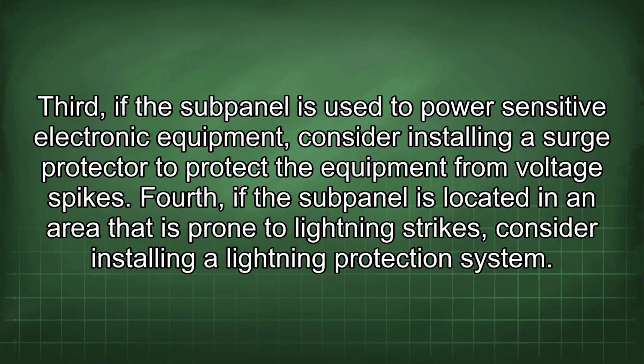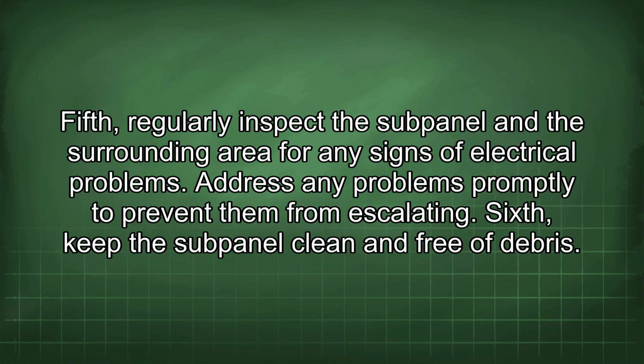if the subpanel is located in an area that is prone to lightning strikes, consider installing a lightning protection system. Fifth, regularly inspect the subpanel and the surrounding area for any signs of electrical problems. Address any problems promptly to prevent them from escalating.